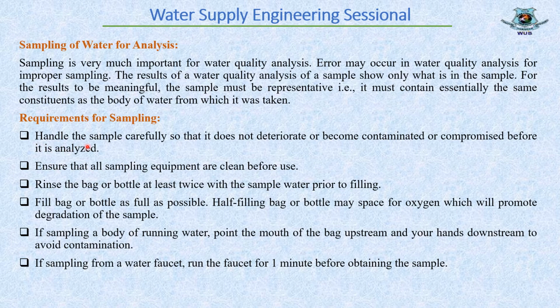First, handle the sample carefully so that it does not deteriorate or become contaminated or compromised before it is analyzed. Then, ensure that all sampling equipment is clean before use to avoid contamination. Rinse the bag or bottle at least twice with the sample water prior to filling, so that the collected water does not mix with any good or worse quality water and the results deteriorate.